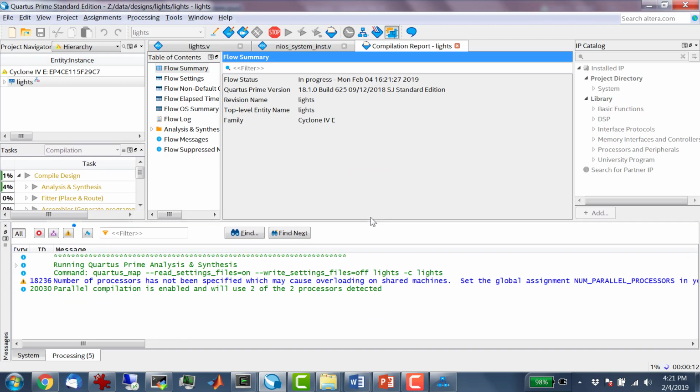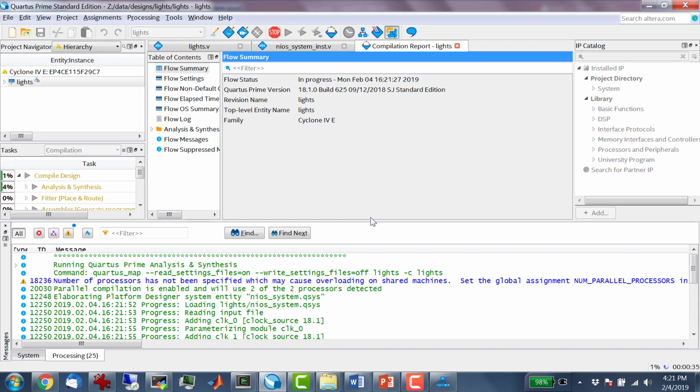Okay, now while that's running, we have to go back and revisit the software, because I changed the platform. I added those peripherals, the UART and the GPIO pins. The BSP, if you remember from last time, is the board support package, but it's really a hardware abstraction layer. It's kind of a very thin operating system. It's going to provide some hooks, some functions I can call to access the hardware, right?